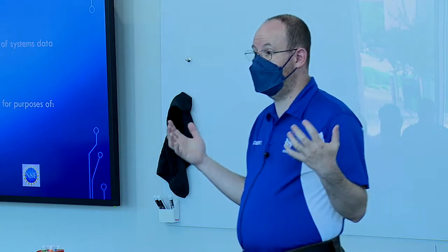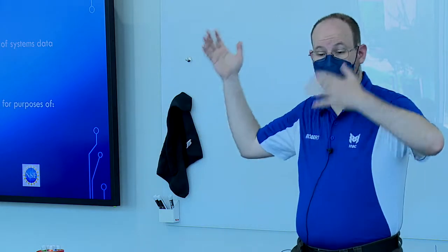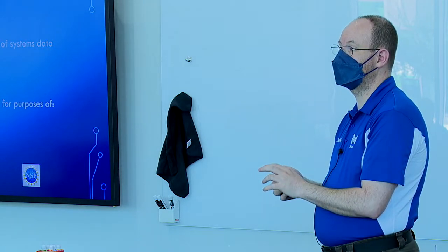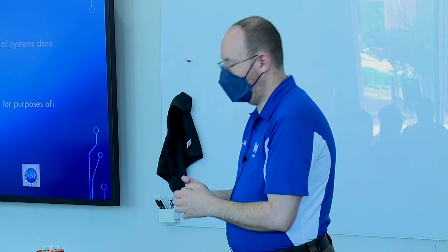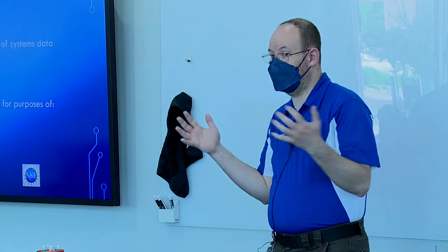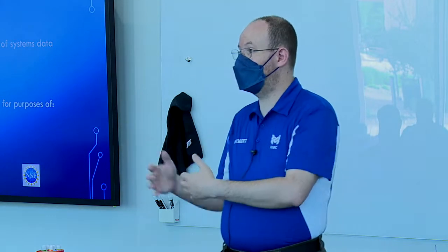Because everybody's definition of a critically controlled space is different. Everybody will agree, data center, wiring closet, those, we all agree, those are important. The refrigerator, the beer cooler, right? But the key is the trend logs are going to tell you how to fix the problem. You're absolutely right. The trend logs are key. They are such an amazingly useful tool in the technician's tool bag from a building operator standpoint, from a service standpoint, but they rely on being properly set up on the front end.